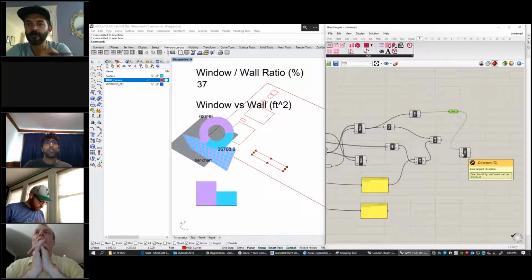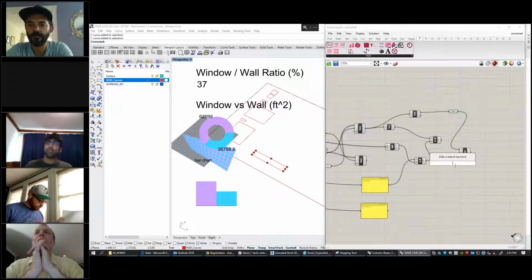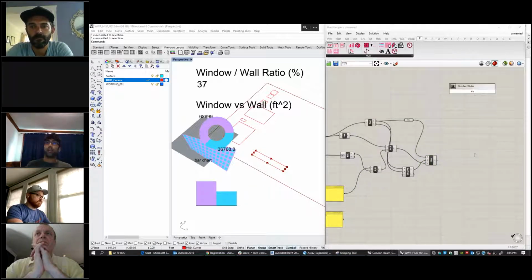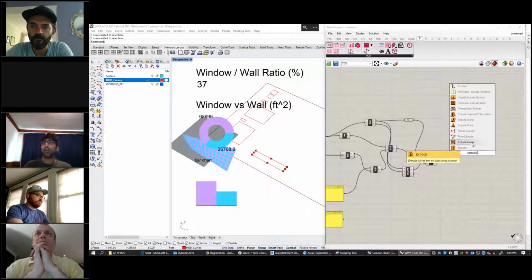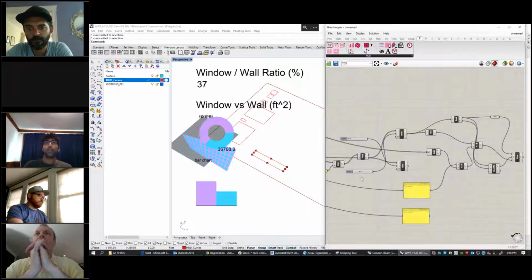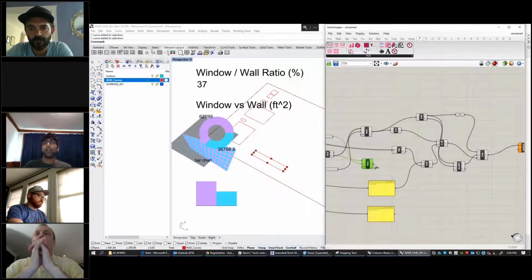And then the direction is going to be, let's make a vector that's 2 points and use this whole start and vector, right? So we know it's pointing now in the direction of that long line. And then the length is our nice number, right? So now we have a nice line that is this number. So now we can extrude this curve that we have along our short line, which is this guy, right?